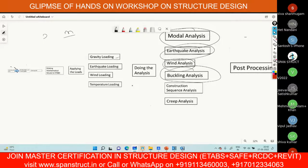Okay, so what is happening here? Due to the structural configuration, a structure may get buckled. Let's suppose you're building a circular structure. Due to this shape, the structure may experience some buckling load due to its own shape. So for such structures, we have to calculate the buckling load and perform the buckling analysis also.